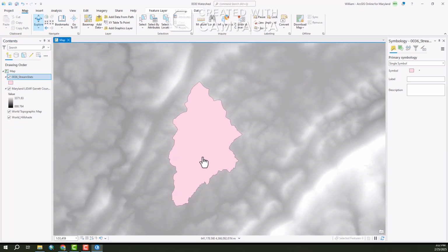Now, why don't we use this shapefile? Well, as I said, this is based on pretty big cells for this watershed. It isn't really accurate around the ridge lines, but it's close enough for us to get an idea of where the ridge lines are. So what we will do now is create a clip file around this file so that we know that we have the ridges taken care of, and we can use a smaller DEM file. But first we have to create a clipping shapefile.